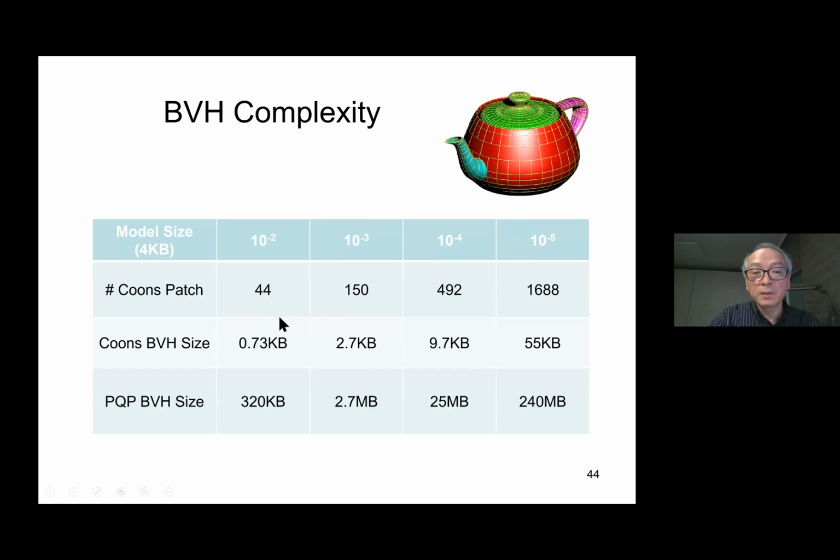when you divide a certain patch into two pieces along the U and V directions, we generate 4 times more surface patches. And cubic approximation order means that the approximation error will be reduced 8 times. But even if we increase precision 10 times, it does not really increase 4 times. So practically, it is maybe more than cubic.